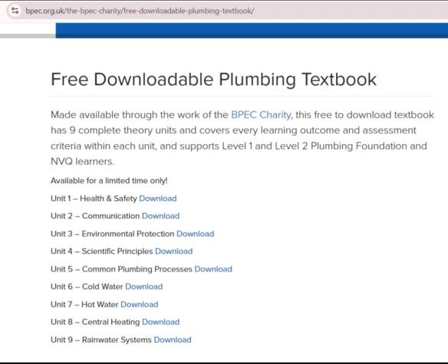Air velocity. The air velocity refers to the speed at which air travels through the building. If the air is traveling too quickly, the occupants will feel a draft. If the air is traveling too slowly, then the air change requirements for the building will not be satisfied. The optimum velocity is 0.2 to 0.25 m/s.